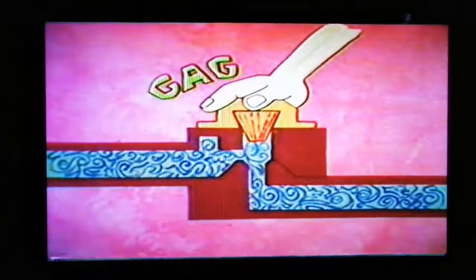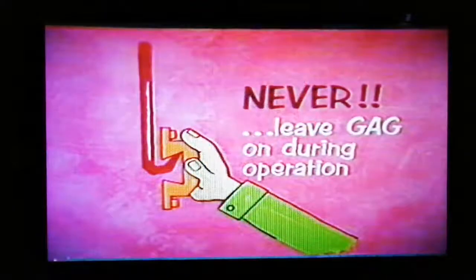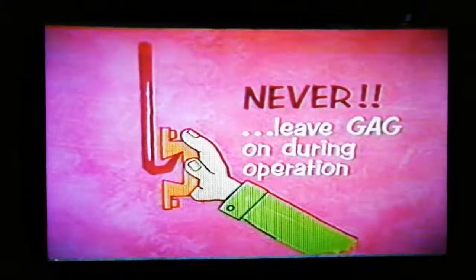As a little side information here, a device called a gag is used during hydrostatic testing to hold the safety valve closed while being overpressurized during the test. The gag should never be left on the valve during normal equipment operation.